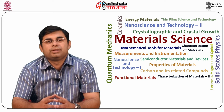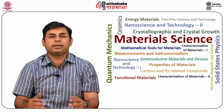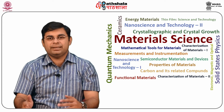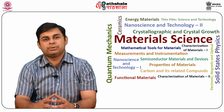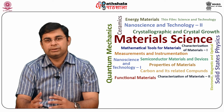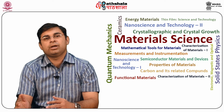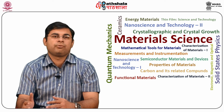Capacitive transducers. A capacitive transducer is a variable capacitor whose capacitance is varied by a non-electrical quantity being measured. The capacitance C for a parallel plate capacitor is given by the following expression: C is equal to epsilon naught into epsilon R into A divided by D farads. This is equation 4, where epsilon naught is the absolute permittivity of free space, which is equal to 8.854 into 10 raised to the power minus 12 farads per meter.